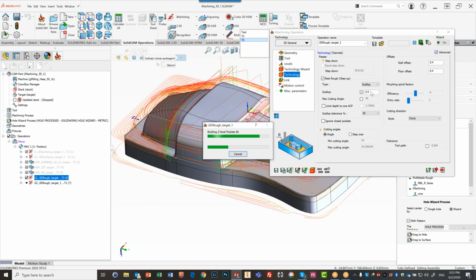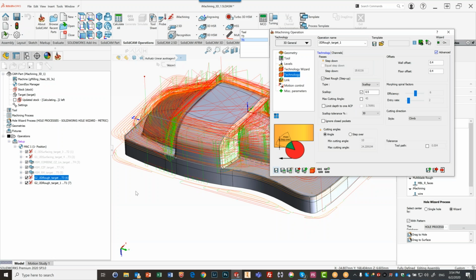It's still big. Yeah. Depends on the area that you want to achieve. True. But when you're talking with a ball end mill, it's a lot smoother for when you do semi-finish and then you finish cuts with the different options in any case. Yeah, but you're using a ball 6 after diameter 12, so you need to consider that you have another 3 millimeter per side for the bonus operation now. Because if you're going into the corner over here, well, we'll see exactly what happens. Yeah. Okay.